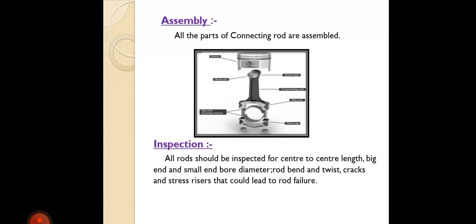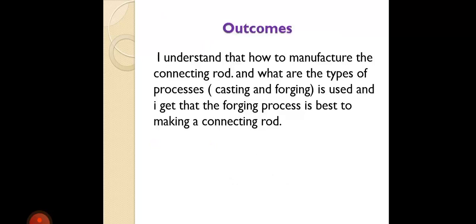Then inspection. All rods should be inspected for center to center length, big end and small end bore diameter, rod bend and twist, cracks and stress risers that could lead to rod failure. Finally, the manufacturing process of the connecting rod is completed.